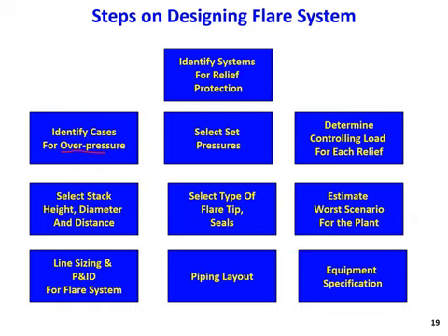Set pressure, for example, for the reactor that I already gave you as an example. For each equipment like the reactor that has a gas phase, we have a safety or relief valve that comes into action when the pressure increases, and it releases the gas that usually goes to the flare system.